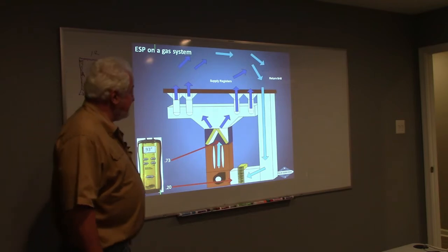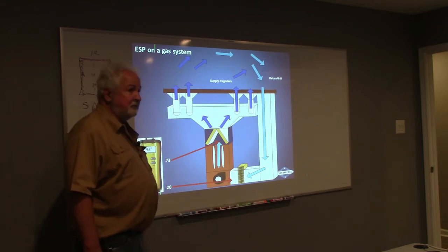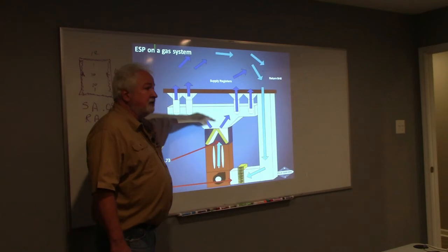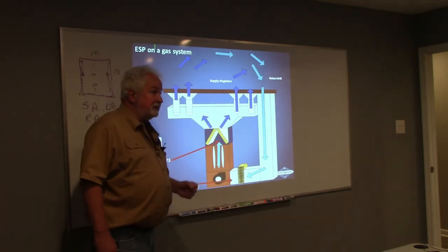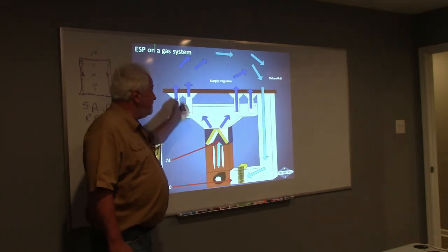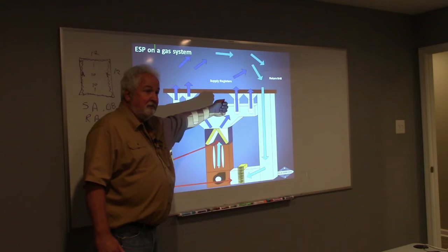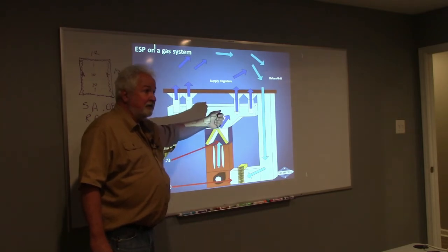I've got a lot of static where? On which side of the system? It's all on the supply, is that right? It might be more supply ducts, is that right? Could very well be. Could be that the grills are all closed, is that right? We don't ever have customers that close grills.